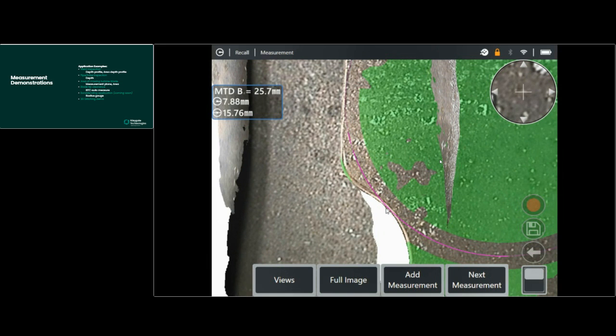it does not conform to this radius criteria. So this is a portion of material that would need to be addressed in order to blend out some more material that you can see between the actual blade surface and this magenta line associated with that radius of twice the blend depth.